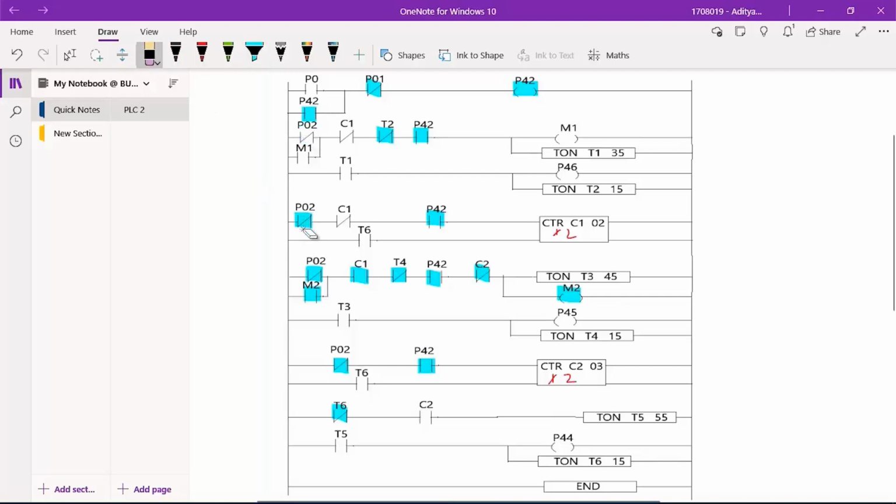Obviously T2 will lose the signal after some time, but T3 will continue to receive the signal, and after 4.5 seconds, T3 is activated, T45 is activated, and the object is pushed by the second cylinder as we expected. So, even if we decide to stop the conveyor belt after sensing one or two objects, the sequence will not break when we resume it.